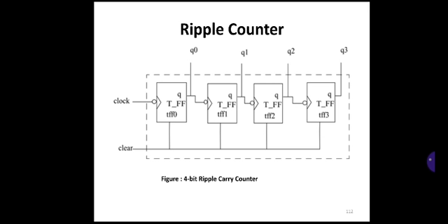In the first module we already discussed the hierarchical modeling concept at a very abstract level. Now we are going to design this 4-bit ripple counter using Verilog. You can also test it by writing the stimulus, but here we are going to discuss the Verilog HDL program.